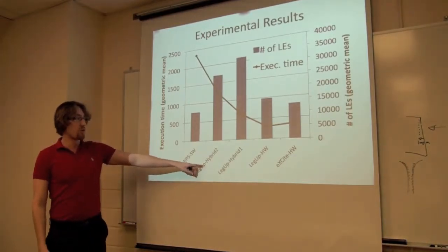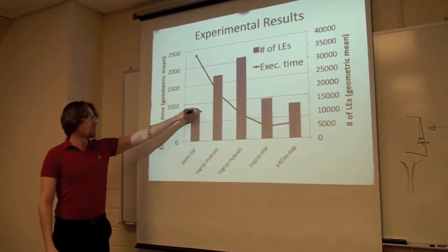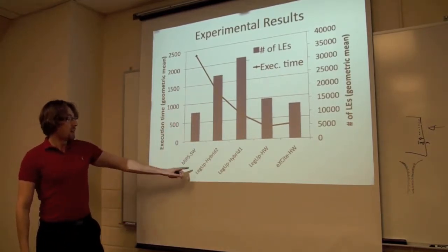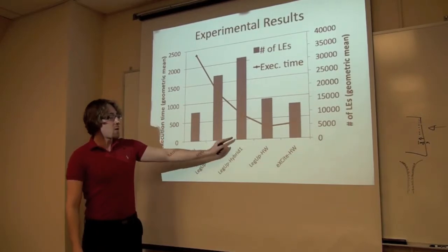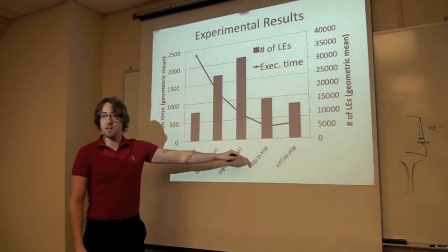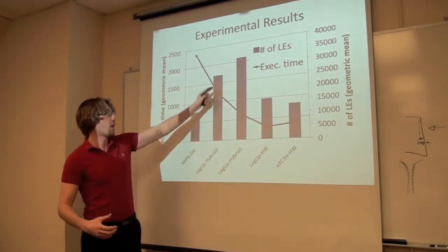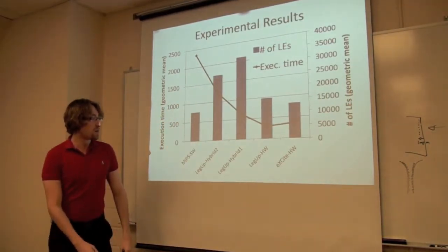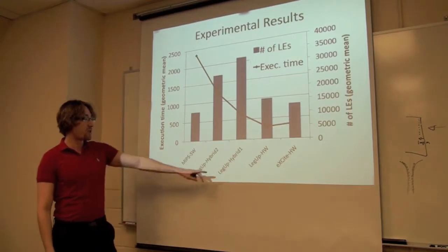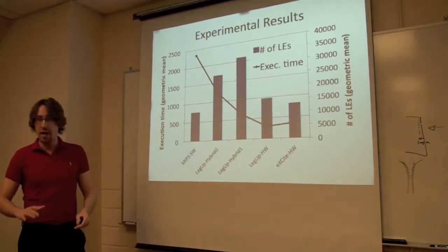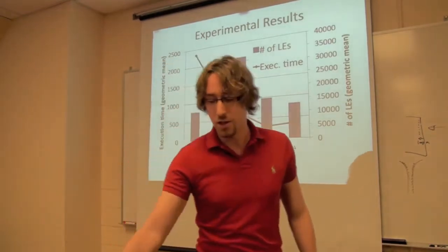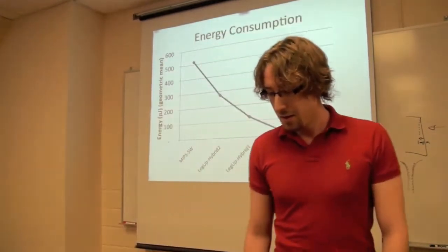As you push more and more of the program into hardware, your area needs to increase because now you have these hardened segments of the program. But then when you go from these hybrid solutions to a pure hardware implementation, you no longer need the MIPS core. So the area drops in this case. And the execution time for the pure hardware solution is about 8 times faster than pure software, on average, like geo-mean average over the benchmarks.